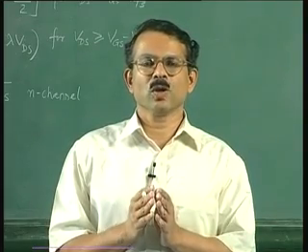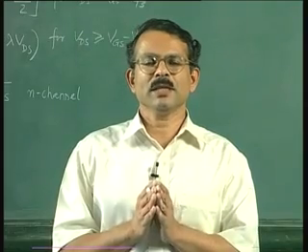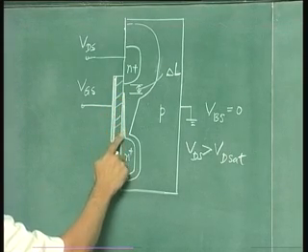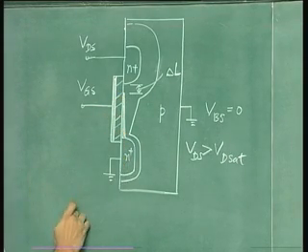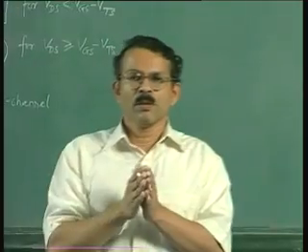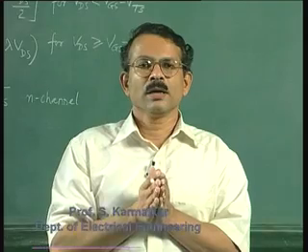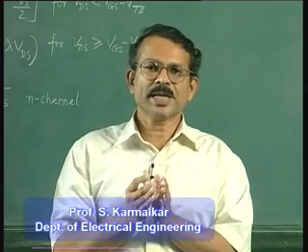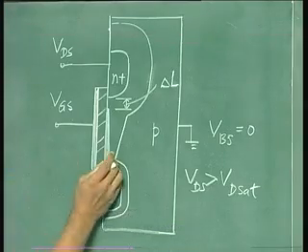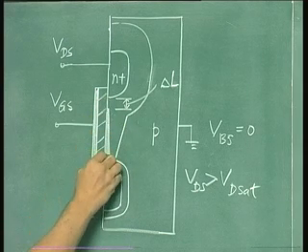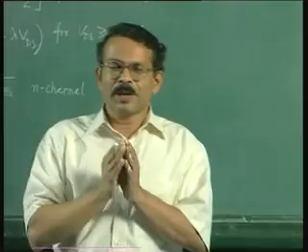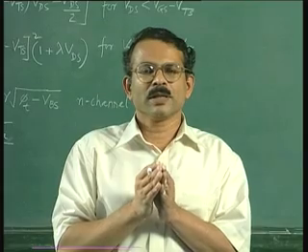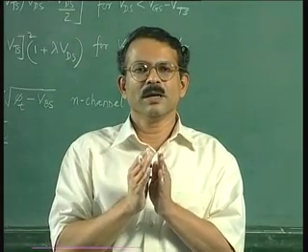the physics, the equations and so on, we have developed assuming a surface channel MOSFET. So here this charge that is carrying the current is because of the inversion layer. Now this kind of analysis also works for buried channel MOSFETs in an approximate manner, but otherwise, in a buried channel MOSFET wherein the channel is because of a doped layer here in this region, in such cases, particularly when the doping depth is deep, or the thickness of the channel from the interface is more,